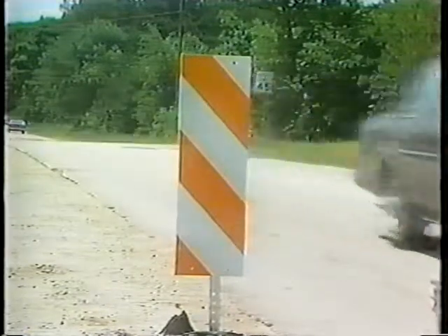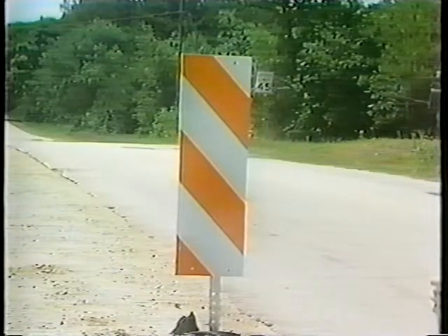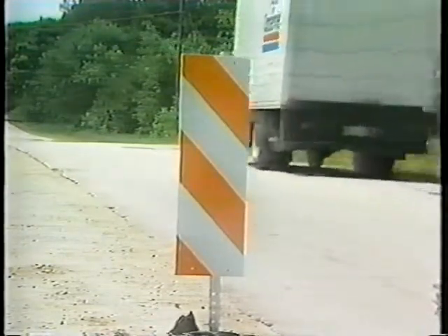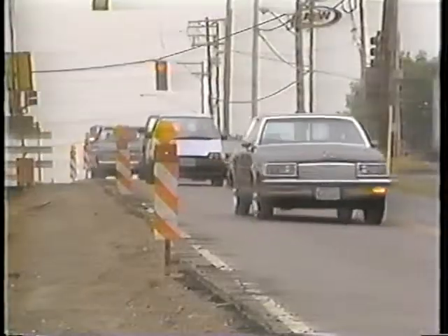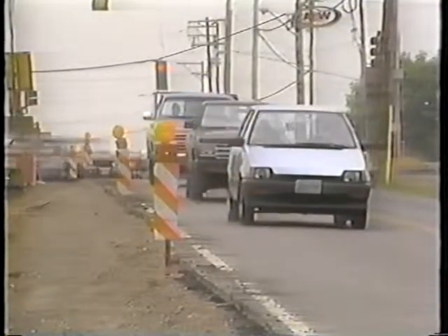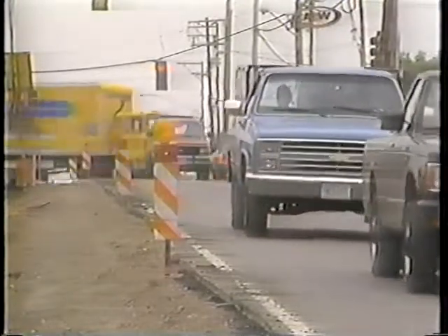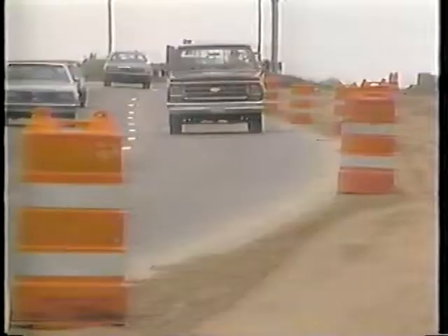Vertical panels are used as either channelizing or warning devices, but are not as portable or easy to install as cones or tubular markers. They are useful in narrow areas where barricades and drums would be too wide. Vertical panels should be mounted on lightweight posts, driven into the ground, or placed on lightweight portable supports. They may be mounted back to back and used between opposing lanes of traffic.